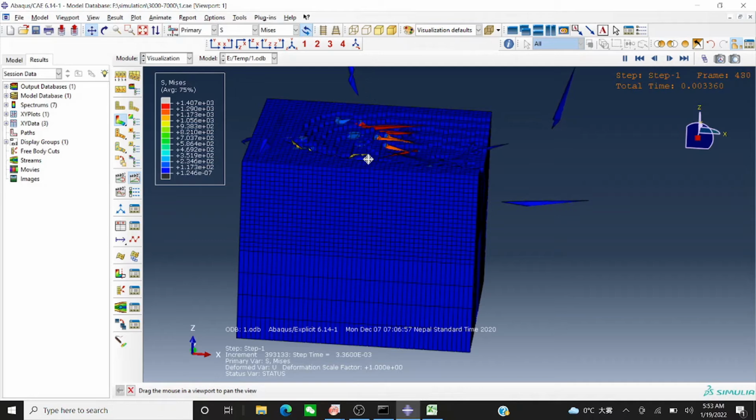Imagine your workpiece has a low specific temperature, but when you are machining it during manufacturing, if your tool is producing a high temperature, it can easily damage the surface of your workpiece. So no one wants irregular surface finish during manufacturing. So it has to be studied properly, and you have to find a proper tool to reduce the temperature. So that is why this is very, very important in terms of manufacturing science or material science.